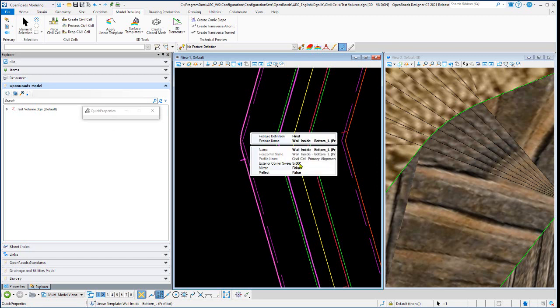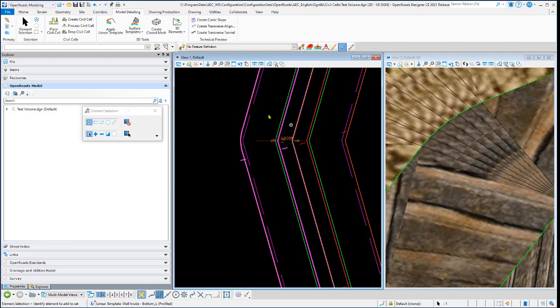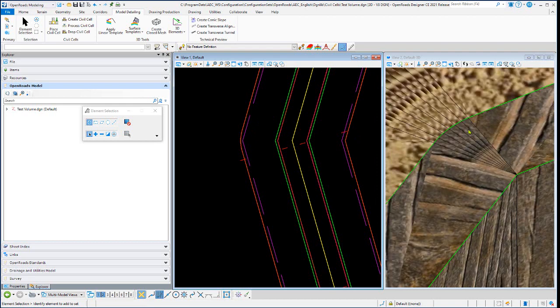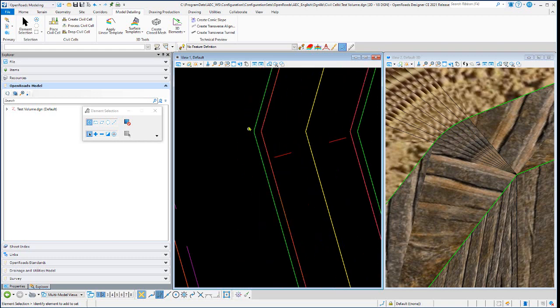I've kind of fooled with it in this particular scenario, and I never could get it to do exactly like I want there. So I think if you want to clean that area up on the outside there, just come in here and manually draw the outside edge. If it's half a foot over, manually draw that, and then complex that little piece, and then add a point control for that template outside top point to follow that element horizontally, and I think you'd get a nice PI out here.